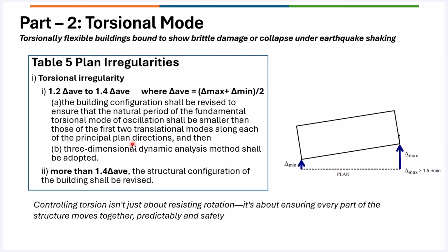The reason is the distance, or the radius of gyration. You can say that for the radius of gyration of the mass and the radius of gyration of the stiffness, if that ratio is greater than 1, then the building is torsionally flexible. In simpler terms, for practical purposes, we can use the time periods T1, T2, T3 from the modal analysis.